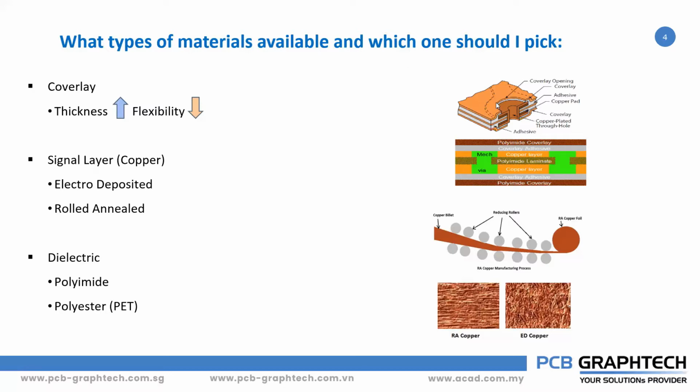So next, a very important thing we have to consider is that we are going for rigid flex design. In the rigid flex design, the thickness is very important. As the thickness of the board increases, the flexibility will start to reduce. So what you have to do in your rigid flex design, if you have a sharp bend in your flex design, a sharp bend radius, in that case your coverlay on the top layer should be very thin. That is very important. So considering a sharp bend radius, the coverlay should be very thin. Okay, so this is the consideration you need to make.